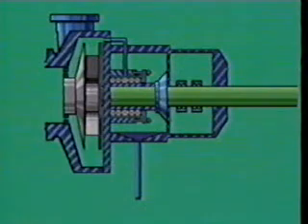Right here, next to the bearing housing, are flinger rings, or shields. They're attached to the pump shaft and fling fluid leakage from the packing gland away from the pump shaft. That keeps the fluid from leaking into the bearings.